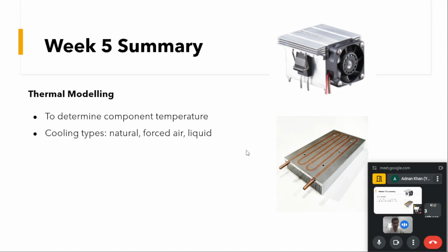The other way of cooling is water cooling, where we'll be having, like you can see here, a heat sink, and in the heat sink will be built-in pipes, and through these pipes a coolant or liquid will be forced to flow, which will extract the heat from the devices, limiting the temperature rise in the devices, thereby preventing any damage to the devices.